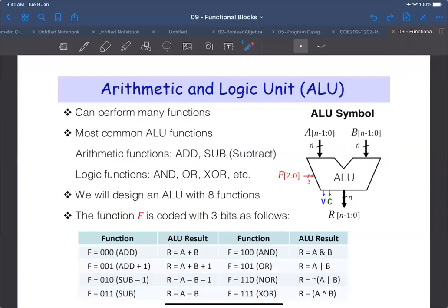The ALU is central in computer architecture. It's one of the major components, and designing the ALU efficiently is a major objective in the design process. One of the things that you really need to do when designing an ALU is to share the components, especially adders. When you do addition and subtraction, you need to do it using one component, one adder for all, because usually adders are very expensive.